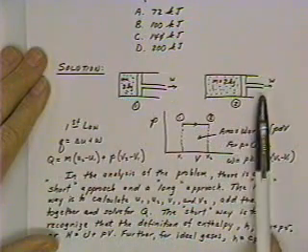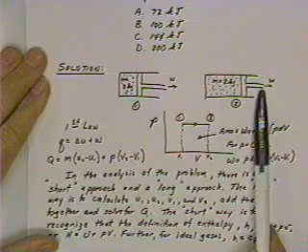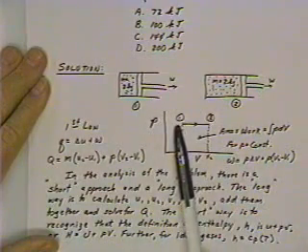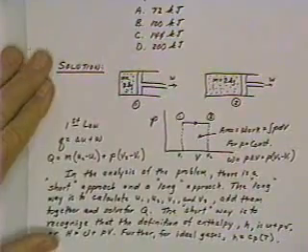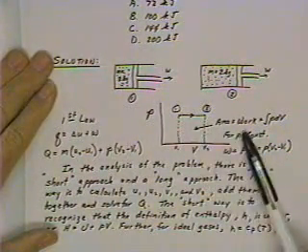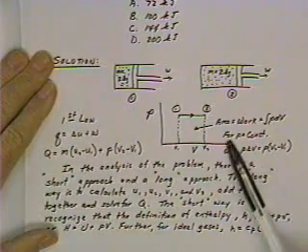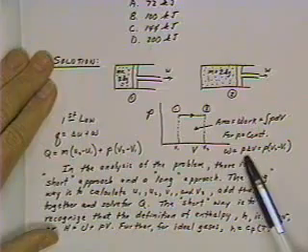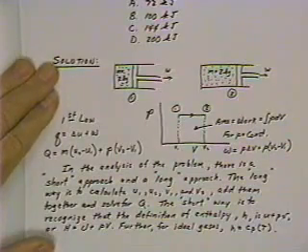Expansion takes place. That means work is being done by the system, so by our sign convention that's going to be positive work. If we sketch this out on a PV diagram, we're starting out with state 1, expanding to state 2. We know that we've got constant pressure involved here, and we also know that the area under the PV diagram is equal to work. So area is equal to the integral of P dV. P is constant, so we can pull it out, and this integral then says the work is just equal to P times the change in volume, or P times V2 minus V1.